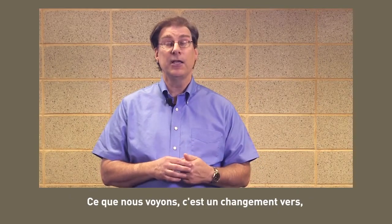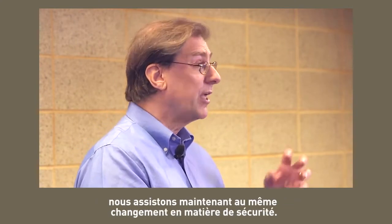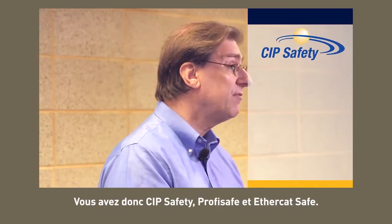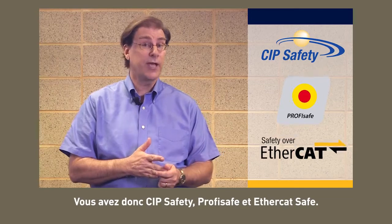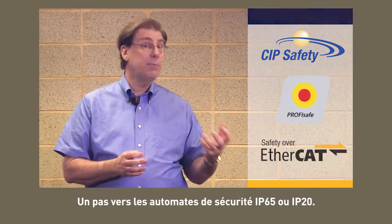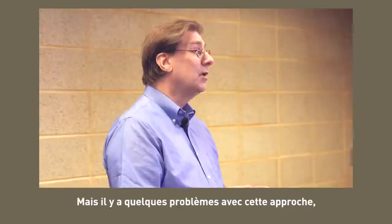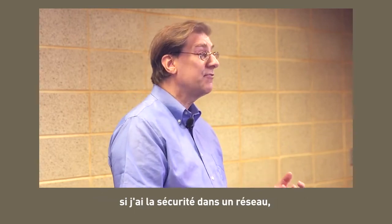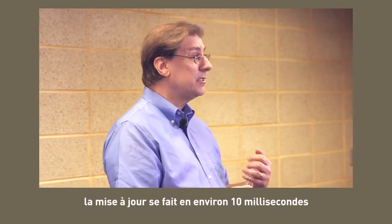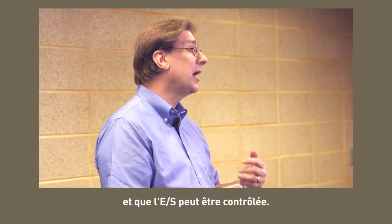So what we're seeing is a shift, just like we've seen from networks, we're now seeing the same thing in safeties. They're going into safety networks. So you have CIP Safety, you have Profisafe, and you have FSoE, Safety over EtherCAT. So it's a move towards that IP65 or that IP20 safety PLC, and everything is coming over the network. But there are some catches to that. If I have safety in a network, I have to make sure that the I/O is still there, so they have a heartbeat, and it updates about every 10 milliseconds to make sure that that network is still safe and the I/O can be controlled.